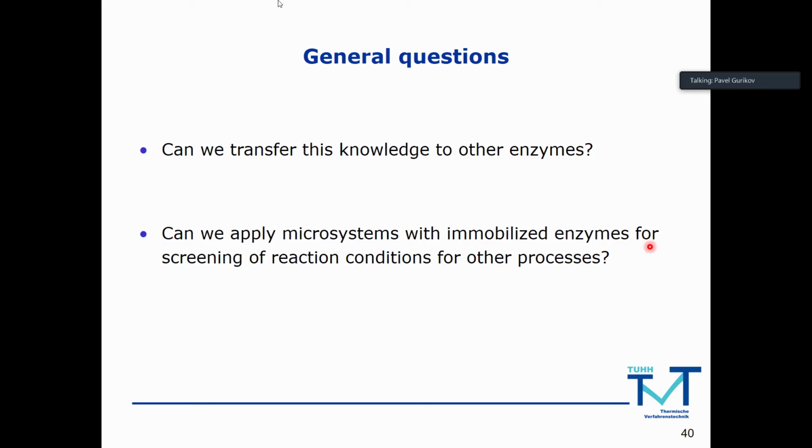That is mainly done for microreactors, because the amount of chemicals you need to use is very small, and you can automatically wash the reactor. So once the reaction is done, you basically flush it with a certain solvent or buffer, something like this, and then it's ready for the next run. In the batch case, you have to clean it, you have to assemble it back. Here in a microreactor you have basically everything set for the operation.